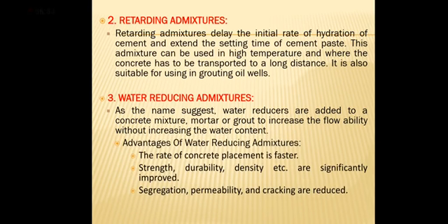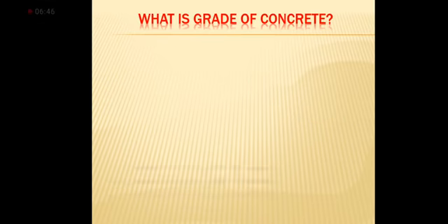Advantages of water reducing admixture: the rate of concrete placement is faster, strength, durability, density are improved, segregation, permeability and cracking are reduced. What is grade of concrete?